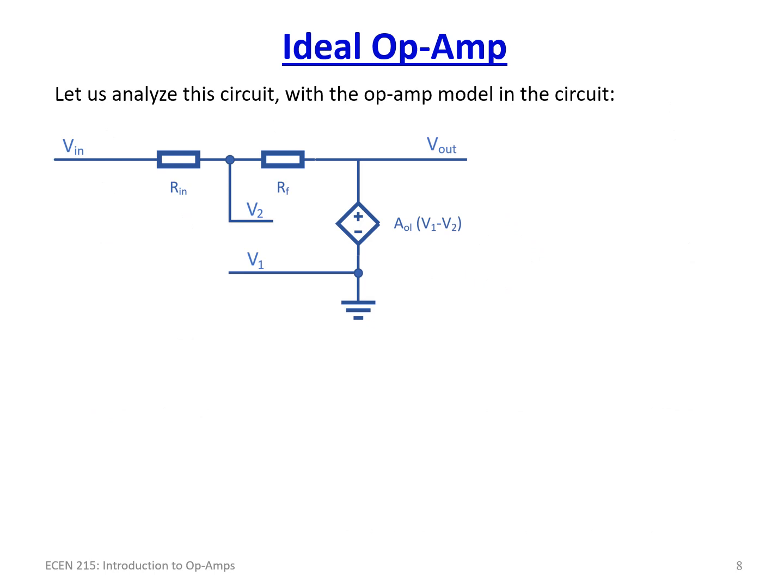We're going to have an input voltage here coming into Rn. So this is just some sort of power supply of some kind. It could be a sinusoid source, something. And it's going to generate a signal Vn. And then we're going to connect our negative input here. So this V2 is our negative input, and V1, the positive input, we're just going to tie to ground. So notice we're just going to hook it straight up to our reference node here.